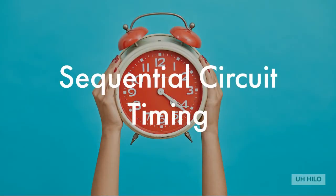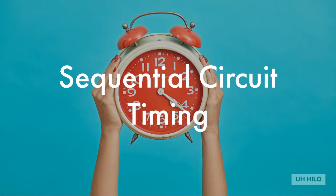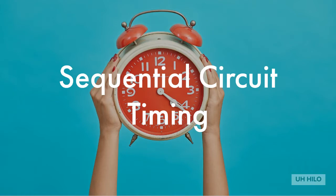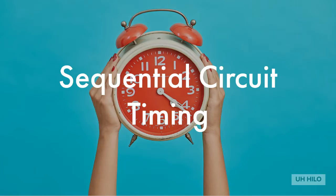There are two ways to analyze performance timing for sequential circuits: maximum input to output delay and the maximum clock frequency. To determine how small we can make the clock period, we need to determine the longest delay from the triggering edge of the clock to the next triggering edge of the clock. We measure these delays on all paths in the circuit where the changing signals propagate.